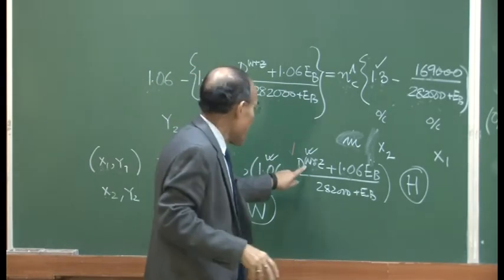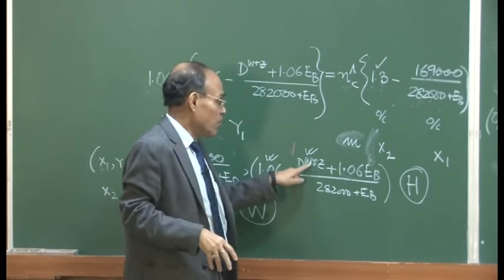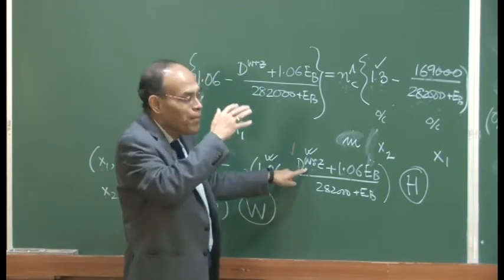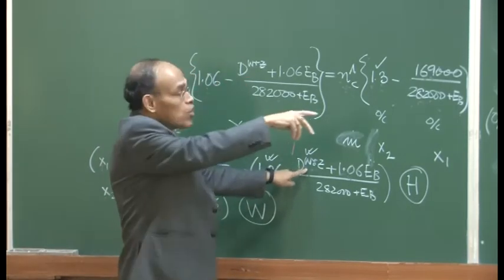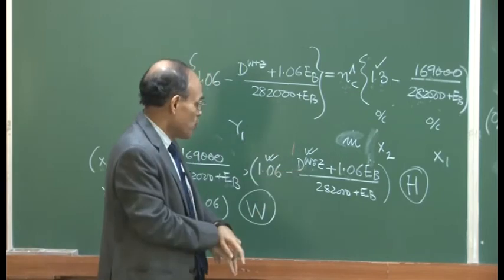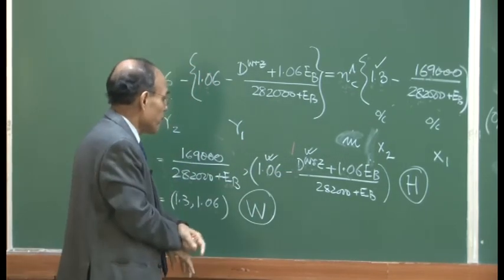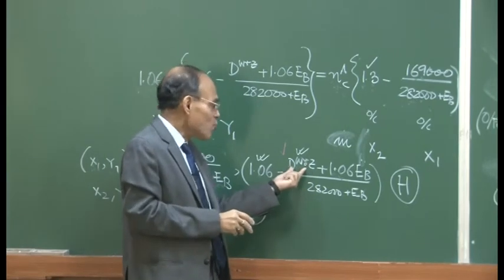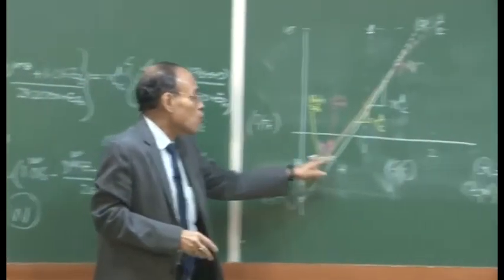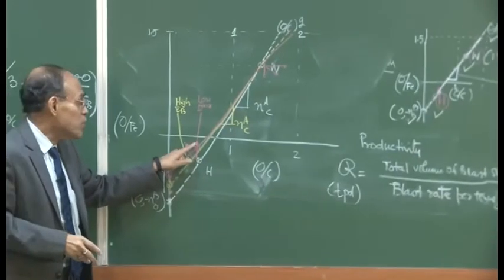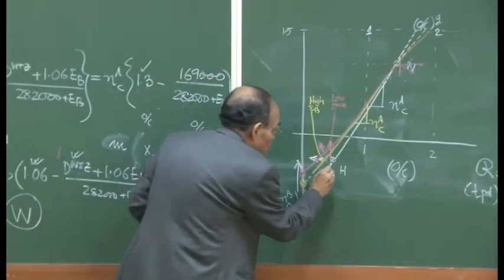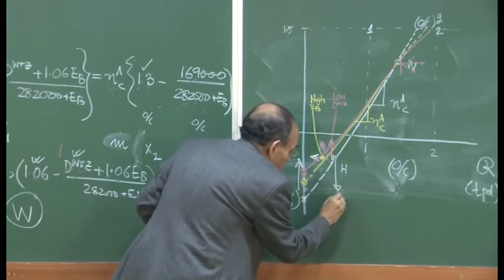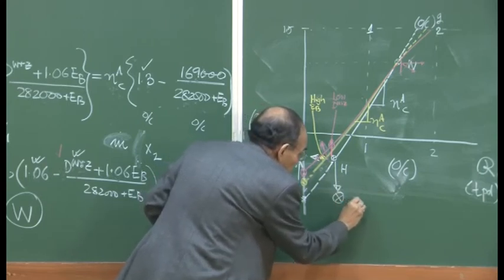So the demand term essentially will include, in the case of a practical blast furnace, many additional terms in addition to those three which I have shown or told repeatedly in this or the earlier lectures. So the moment you reduce dWRZ, the point will move in this way, or conversely the moment you increase dWRZ, the point will move in this particular direction, this is the increased dWRZ.